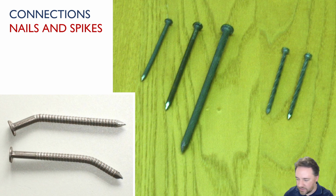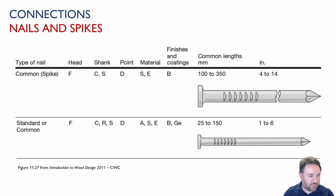Nails come in diameters up to around 4 millimeters. There's nails and spikes. Spikes are just nails that are basically bigger. You can get about 0.5 kilonewton to 2 kilonewtons, something in that range of design load per nail. And so that gives you an idea. Usually for any kind of sizable connection, you're going to use a lot of nails, and you're going to space them out. That turns out to be a very good way to do wood connections, spacing out all of the connection elements, which we'll talk about a bit more in a future video.